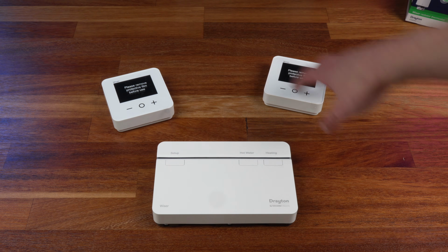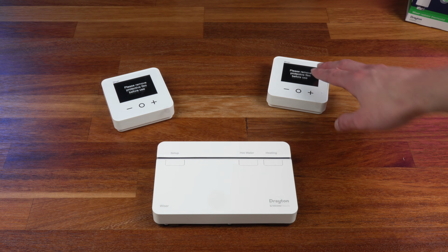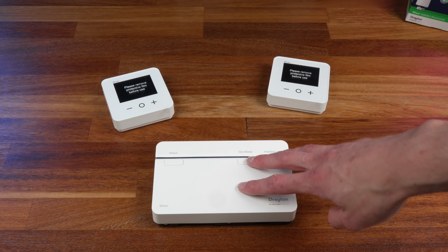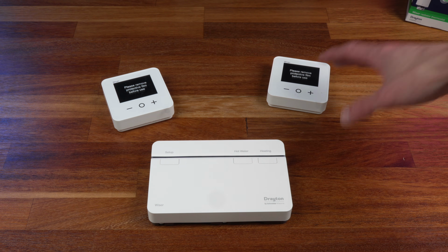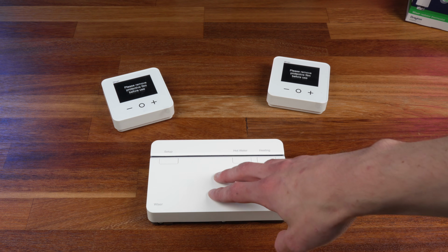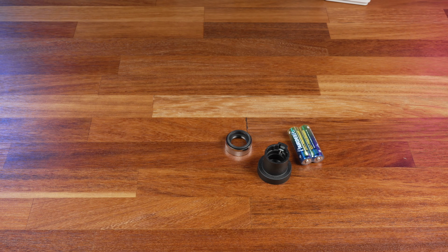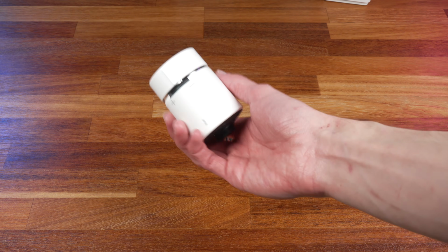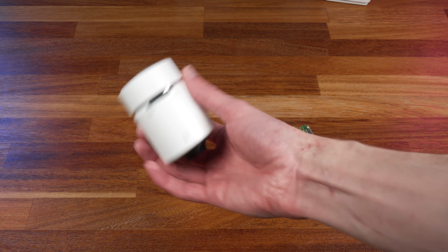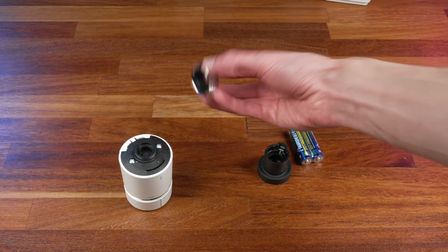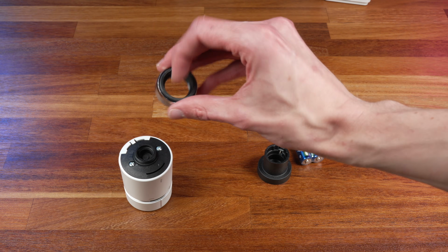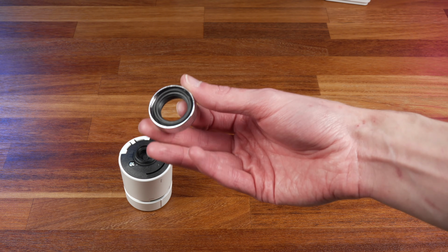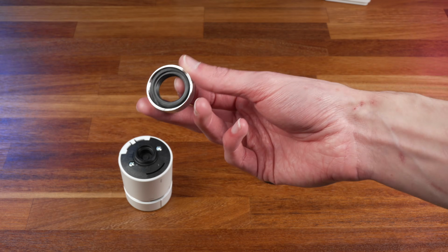These wireless thermostats will take the place of my existing 2-wire thermostats, and then the hub will connect up next to my boiler. The thermostats communicate wirelessly with the hub, and then the hub controls the heating system. I've also bought a total of 4 of their smart radiator valves. So in the box you get the radiator valve itself, you get the kind of bracket and sort of screw mount nut thing that you use to mount it on top of your existing radiator valve, so you take your TRV off and fit this instead.